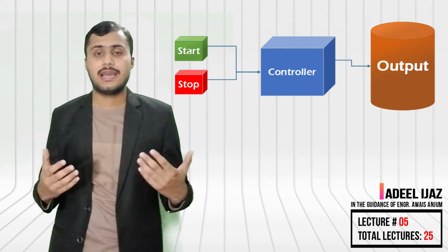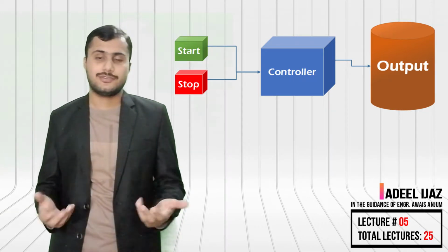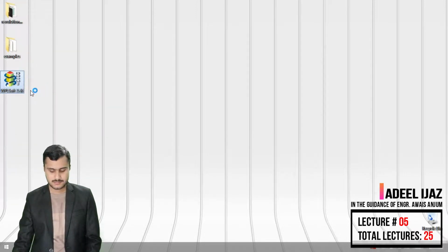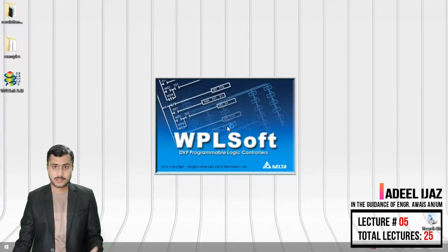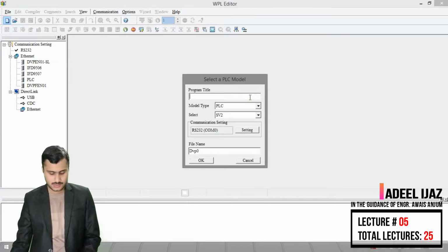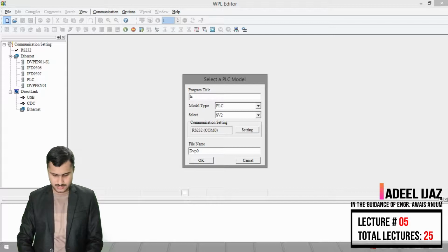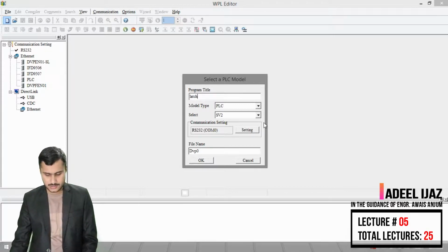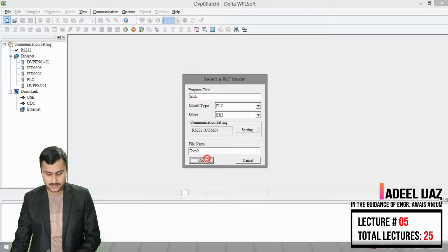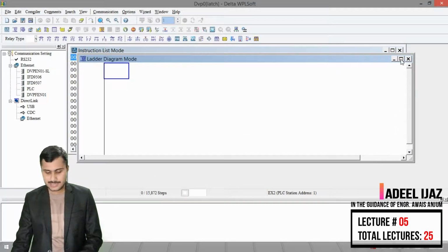To understand it more effectively, let's create a program for this. So here I have my WPLSoft 2.46. Let's open it. Click open. And now WPLSoft is opening. Now create a new project. I'm going to set the title to Latch. And I'm going to select the PLC type to EX2, because mine is EX2. And click OK. Now maximize the ladder diagram mode.